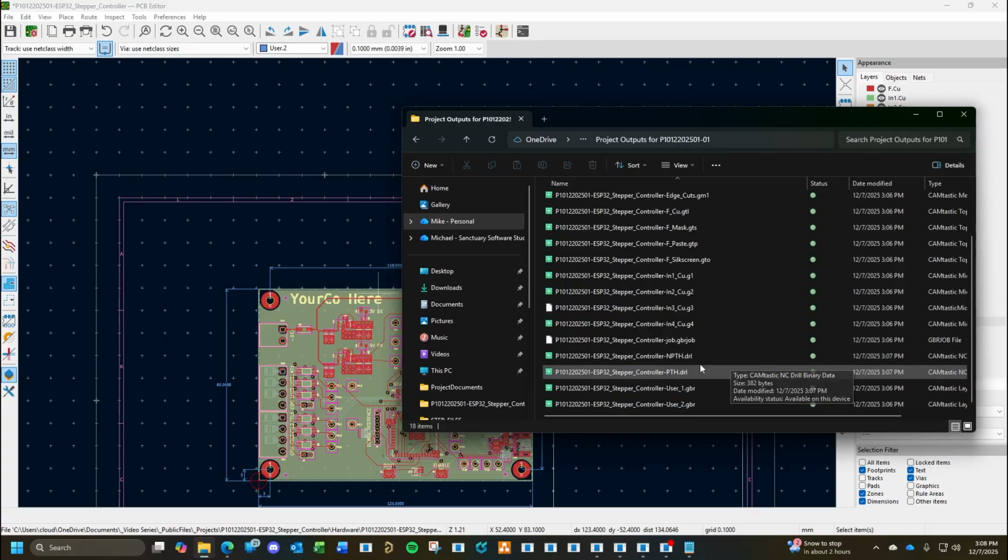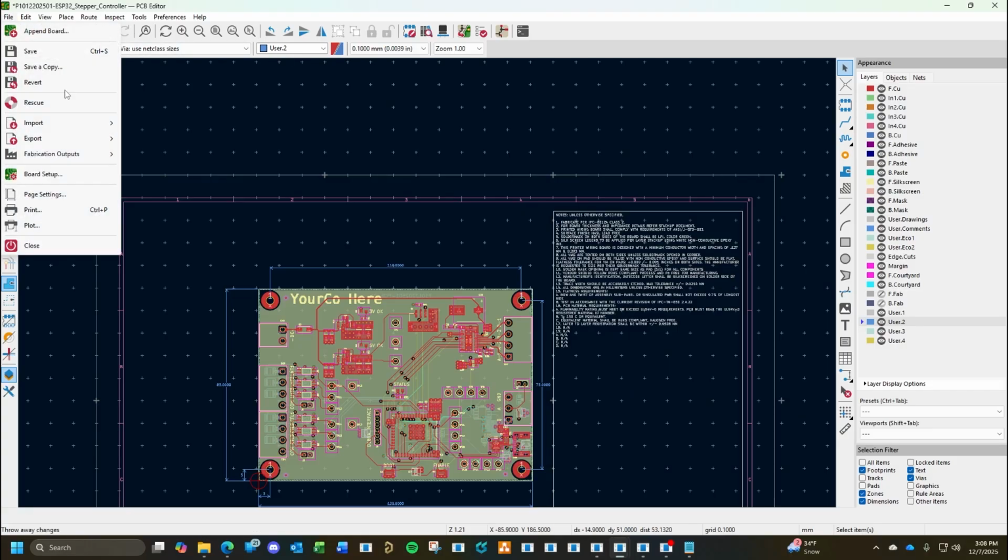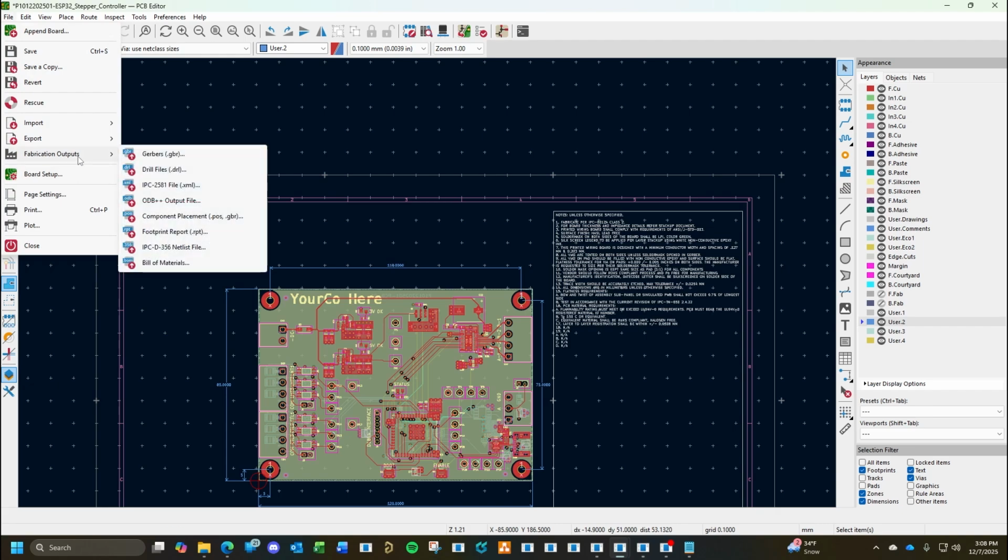That's the Gerber job file, your drill files, and then our 2 user files for the fab notes and the dimensions. So that's that. Now, depending on who your board house is, and you'll learn this as you do this and get set on vendors that you want to use, there's a couple other files you may need. You may need ODB files. You can use the ODB++ files to manufacture off of. It's basically like the Gerber files, but in a totally different format.